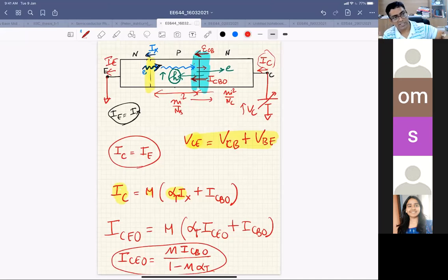And this is a positive feedback process. Electron-hole pairs are generated, holes are collected in the base, and because of the holes collected at the base, more electrons are injected. These electrons create more impact ionization. So after some time, a very high current will flow. Let's say the voltage at which very high current flows is my BVCEO, and the current flowing at that point is ICEO.